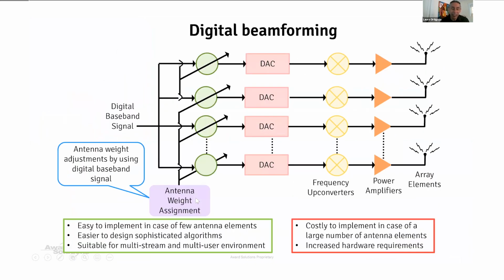the modification of amplitude and phase in the frequency domain, I can create beams. I can create beams for every frequency of operation. For example, guys, let me show you. With digital beamforming, I can create a beam for Bob, right? If I send Bob resource blocks 10 to 20, I can create a beam in that direction because I'm modifying this in the frequency domain. So resource blocks 10 to 20, I'm going to create a beam that way.